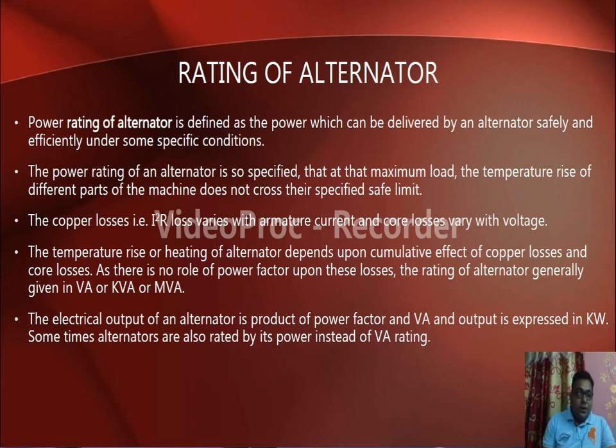I have mentioned a copper loss point here. Obviously there will be copper loss, because there are huge conductors all made of copper, and when a load is connected to the armature winding, a closed loop current flows through the alternator, causing heating and therefore loss. We have to incorporate that loss when finding the power output of a machine.